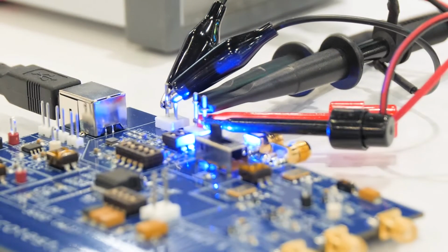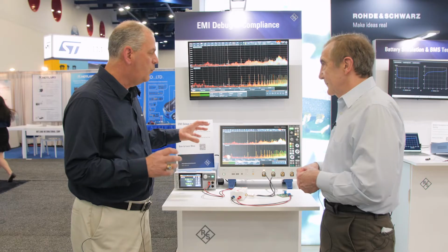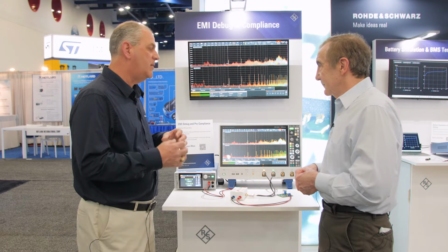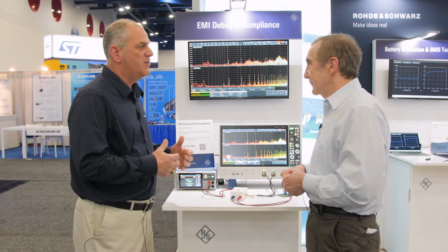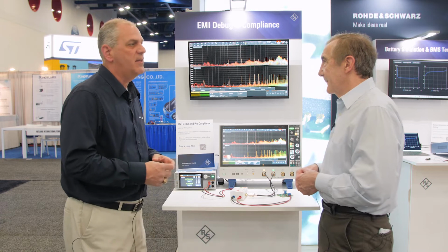So then we're designing our EMI filter for the power supply. We can optimize which components to use and how, so that we can reject the larger interference. Typically you might have a common mode problem. You can use common mode chokes and things like that to overcome it.